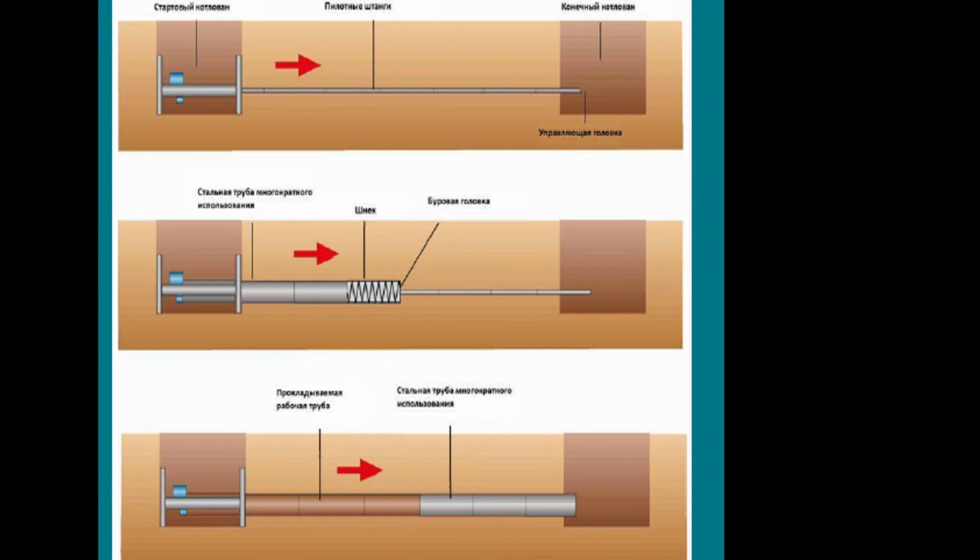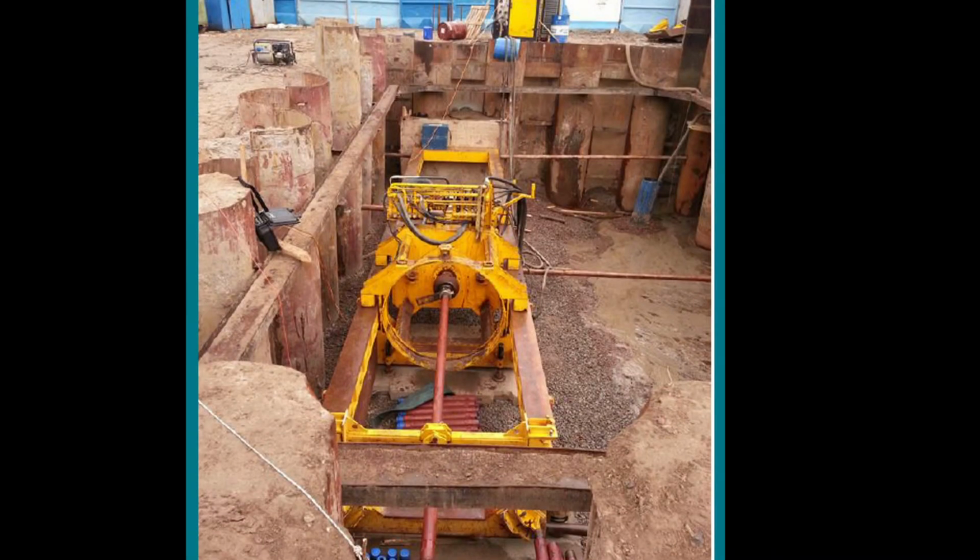Due to the special laser control system, the auger boring technology allows laying pipes with designed inclination with high accuracy. That is important in building of a gravity sewer. The third process we'll be discussing is pipe ramming.